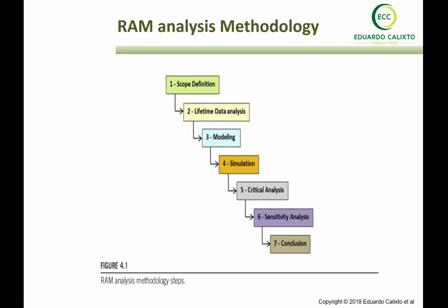So, for example, if we want to assess the performance of one equipment component, we need to be sure that we do not consider failures caused by human error. That's not about the equipment performance. So that's very important when we carry out the lifetime data analysis. We go through the lifetime data analysis in the next modules, and we will go into details about that.